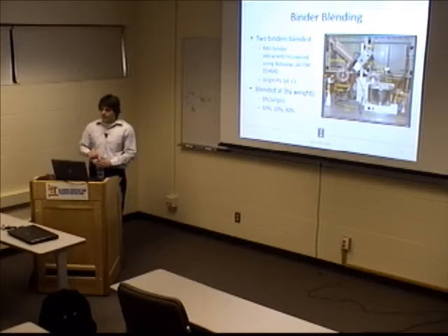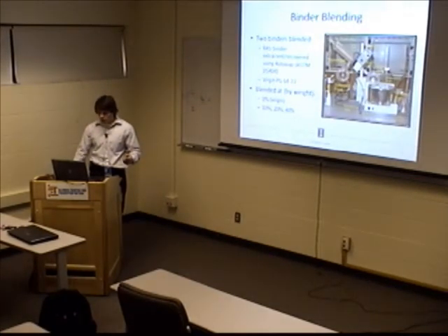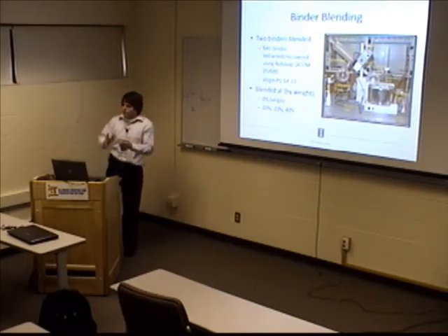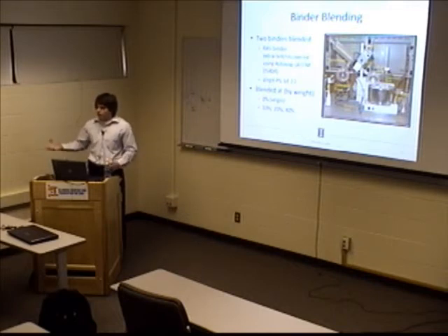Right. But should your further analysis not be concentrating on zero, on how the surface fluctuations are? I guess you could do an analysis based on that, but I think the idea behind Superpave as a whole is that if we have a PG 64-22 binder, and the temperature does not get below that minus 22, regardless of where it is in the country, then we won't have an issue.